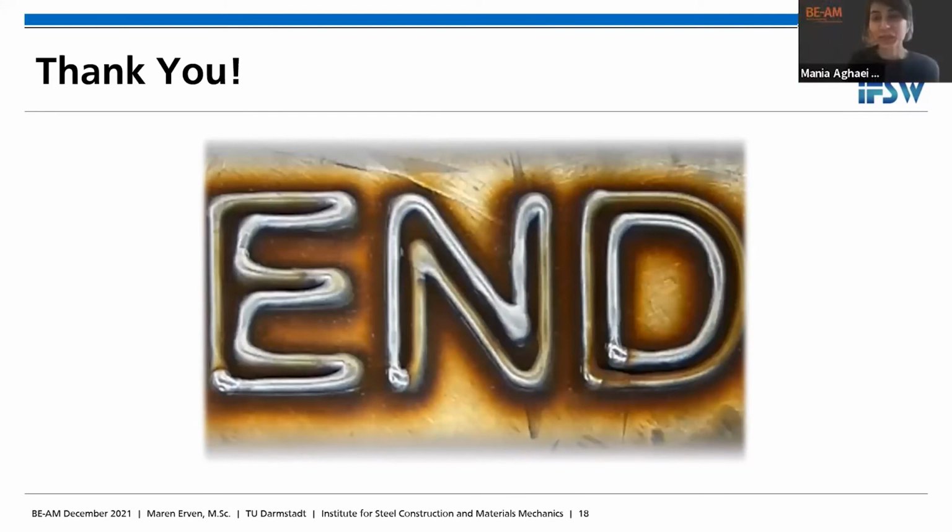Thank you, Maren. Great work. Thank you very much. So a quick question, how do you deal with the challenge of topology optimization generating this complex form with a lot of thin pipes in the air, and then you have the constraint for FDM-based printing with your WAAM printer? Do you go back and regenerate the topology optimization, putting some obstacle on the way to regenerate those new bridges, or how do you actually deal with refining optimization based on fabrication constraints?